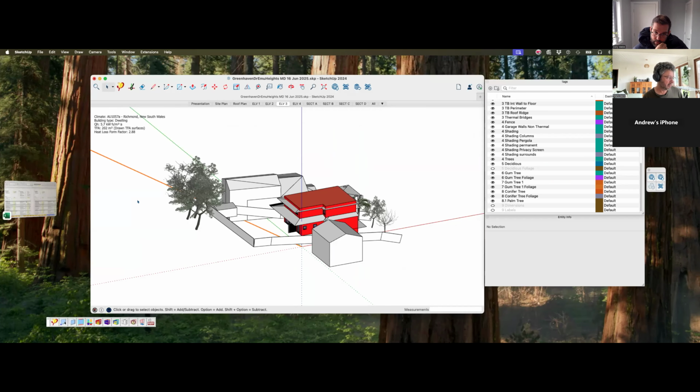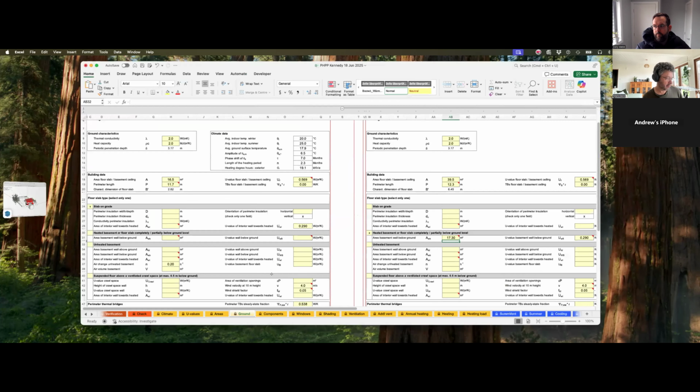Because Andrew, the discussion Mark and I had was, do we make the little section of floor above that access into the garage doorway out of timber because it's a huge thermal bridge? And I just thought, let's just simplify it, get rid of the curve, get rid of the access, and then you can just have the slab come across to the wall, and it's a lot easier. Don't have to do tricky stuff. Yep, agree. So fair enough. When you give me new drawings, Corey, I'll need that obviously in the drawings.